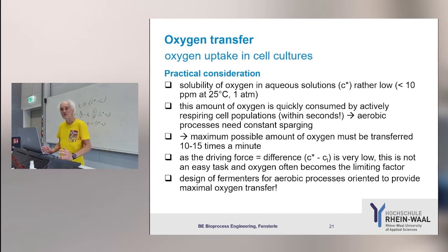So if you stop your oxygen in the reactor, if you have a reactor where you have a high cell density and quickly growing cells, it will be consumed within seconds. This is also the reason why with the Erlenmeyer flask shaking culture, as soon as you reach reasonable cell densities, oxygen transfer quickly becomes limiting. Yeah? This is the reason why you have a bioreactor and don't always put something on the shaker. It's not the reason why. But oxygen transfer is way better in a bioreactor than on a shaker, yeah? Because you have higher surfaces and so on.